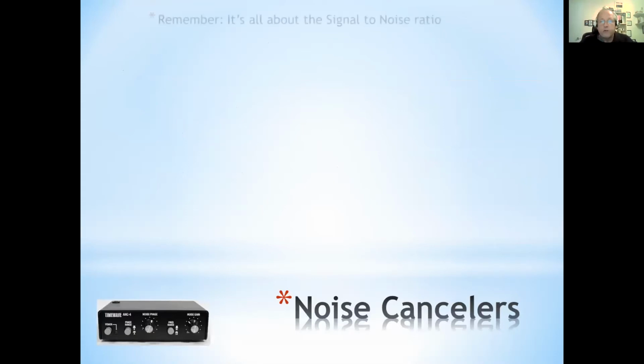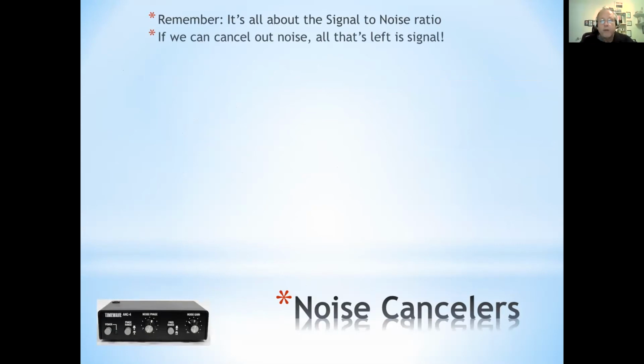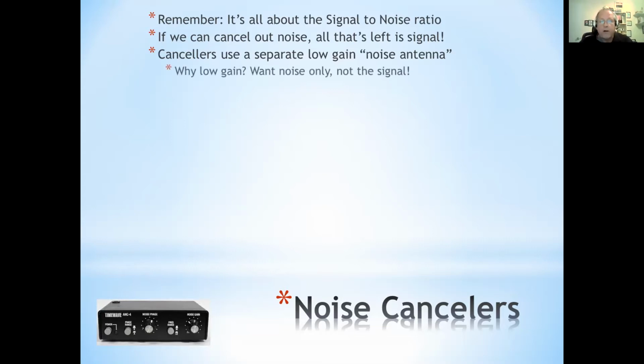So how do these noise cancelers work? Well, remember, it's all about the signal to noise ratio, right? If we can figure out a way to cancel out the noise that's coming in the antenna, all that's left is the signal. Wow, what a concept, right? So what cancelers use is a separate antenna that's just considered to be a noise antenna. It's a really crummy antenna. It's usually as close to the noise source as you can get. It's going to be non-resonant, and it's going to be low gain, right? You don't want it picking up the signal. You only want the antenna to pick up the noise, and we're going to explain why in a second.